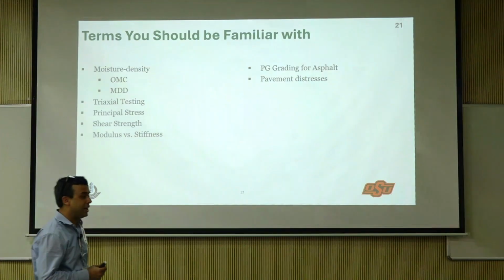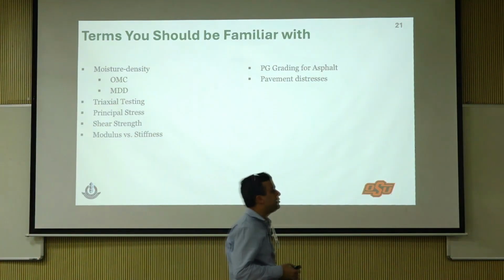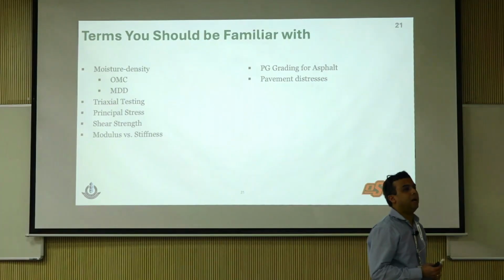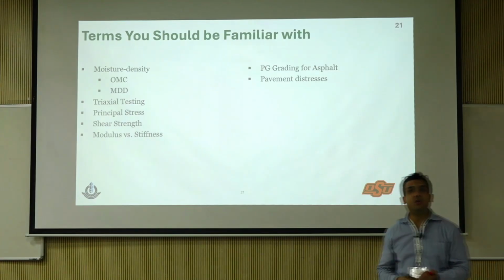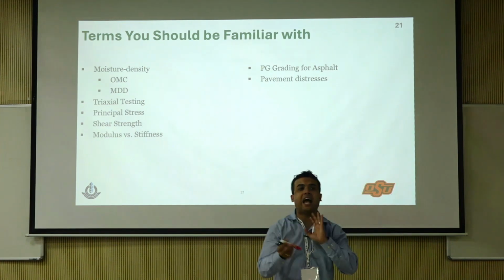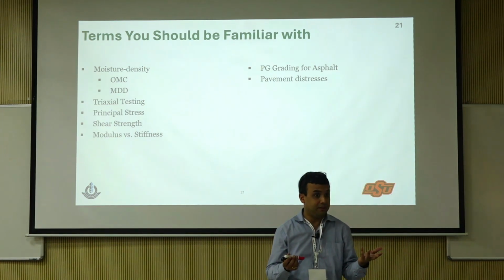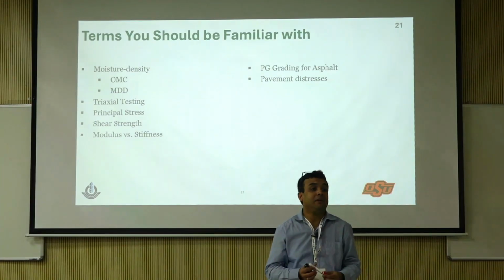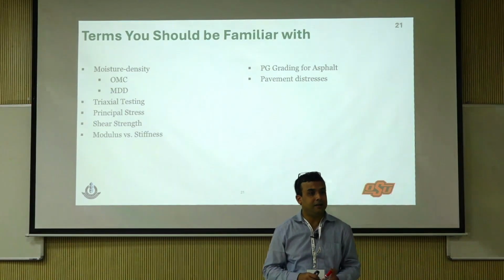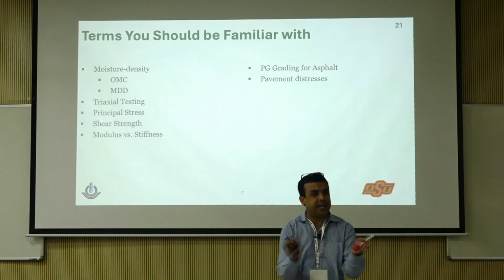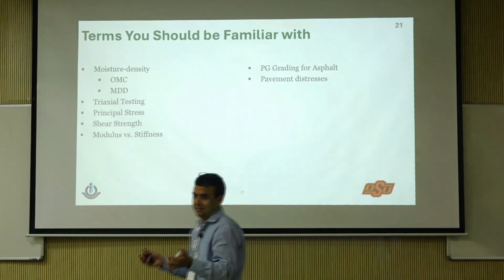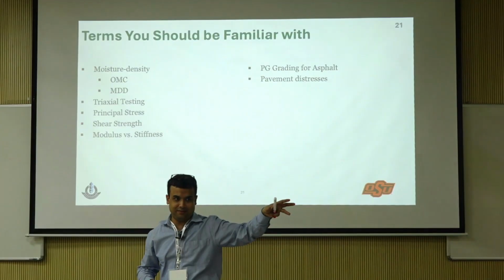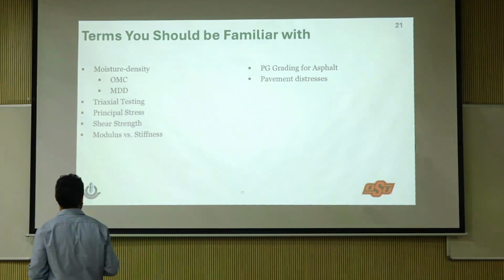Can we relate the response and performance in FEM modeling? Again, it is all dependent on how good your material model is. If you are asking, can I use FEM to predict crack propagation? Yes, you can do that. But again, what is FEM? It's a continuum model, right? The moment there is a proper crack, continuum falls apart. That's where you have to go into discrete models, which is called discrete element and stuff like that.